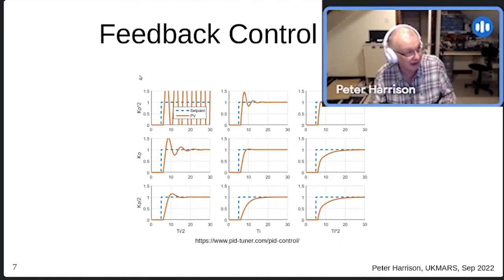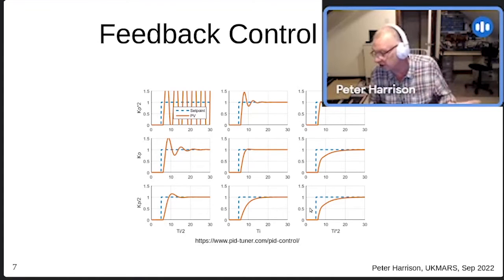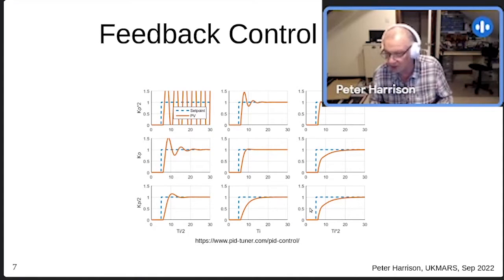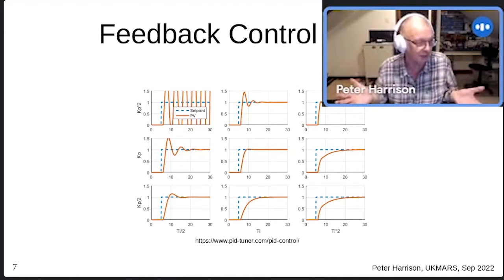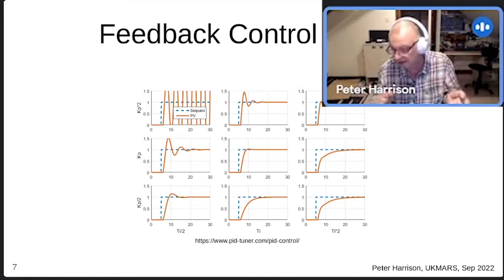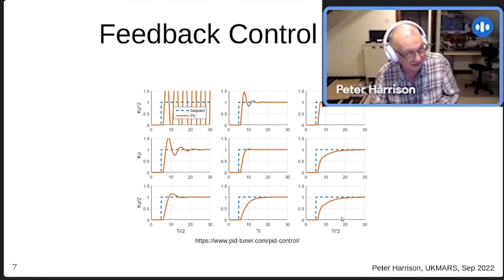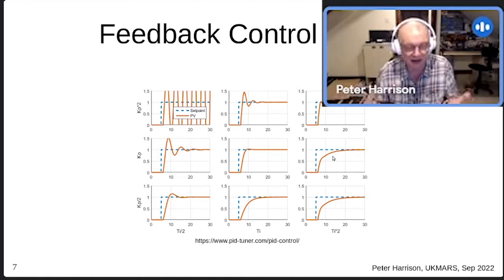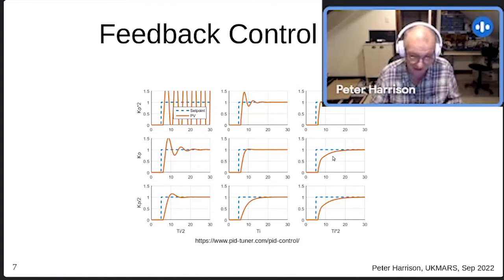There's a P for the proportional, there's an I for the integral, and there's no mention at all of how the D might make a difference, because it's using a different mathematical model to the one that you may have looked up, a statement about the maths of the control loop, and it'll talk about KP E and KD times E minus E dashed and all that sort of stuff. But here they're combined into TI. And anyway, to cut a long story short, PID control loops are a nightmare. People use them, people tune them, they tune them badly, and they don't understand what's happened when they've done it.